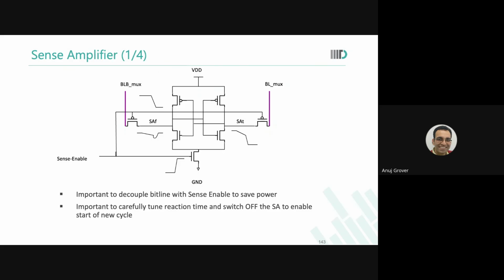You can only charge the circuit, and this circuit can store only as much charge. It's a capacitance. Some node will be at VDD, another node will be at VDD minus VT. All those things will be there, but it's still a capacitance. It doesn't do anything. There is no active current flowing through the circuit if the NMOS is off, if the pass gate on the bottom is off, if the device on the bottom is off. So it's not a latch at that time. You can pre-charge it. It's like a capacitance only. Is that okay? Anything else about the sense amplifiers?